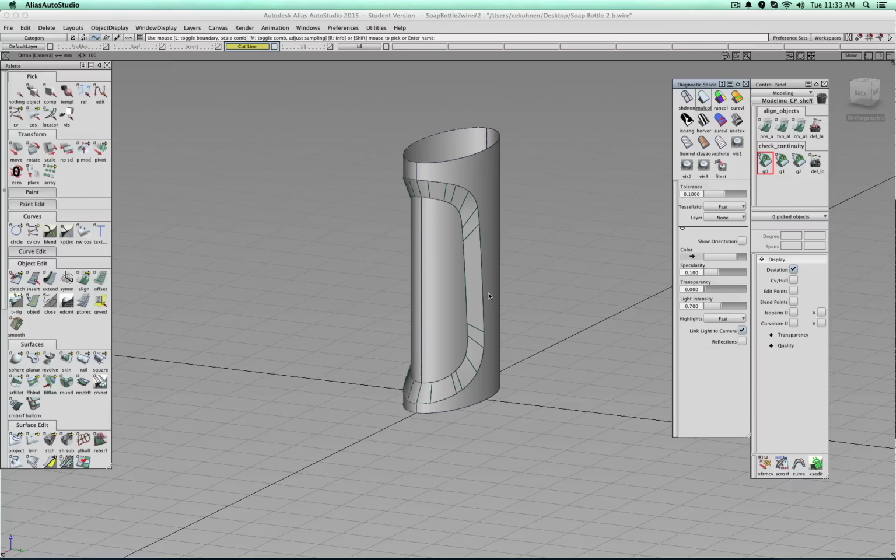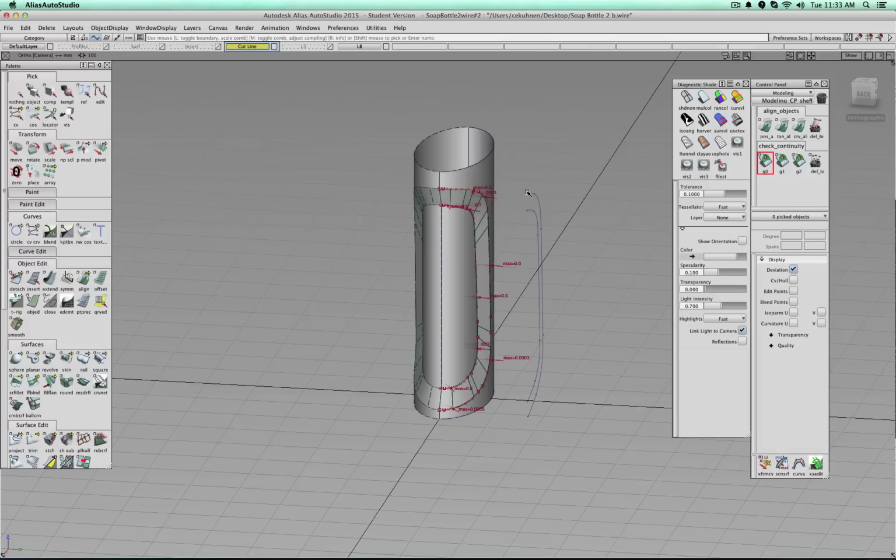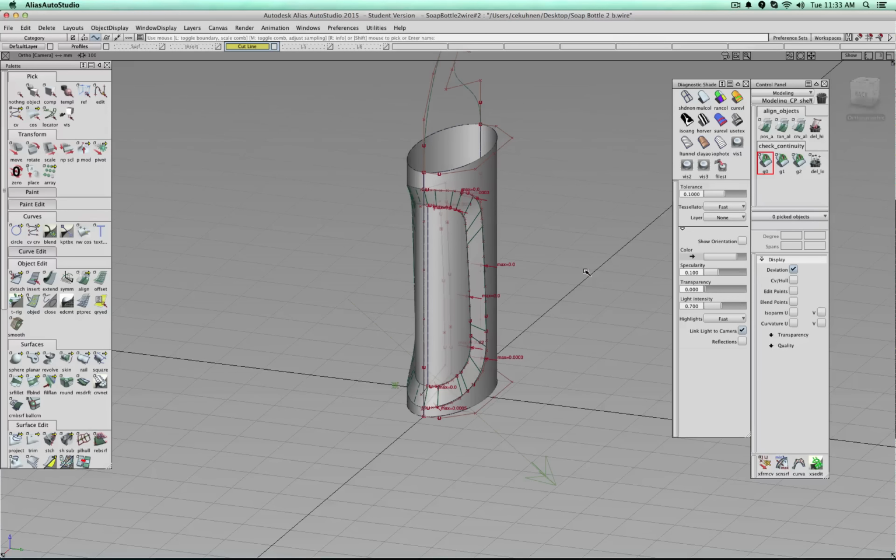And I thought this actually is a good overview to see the problem sometimes you have and why, for example, I work with duplicate curves on different layers. So I try something out, and once it doesn't work, I go back to the layer where I have my master parts, change some degrees, push it back over, and even those curves basically come from the original curves I had somewhere else. Or did I override them? I must have by accident moved them not onto the correct layer.